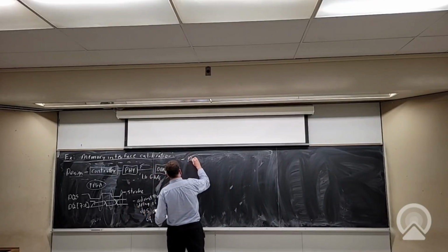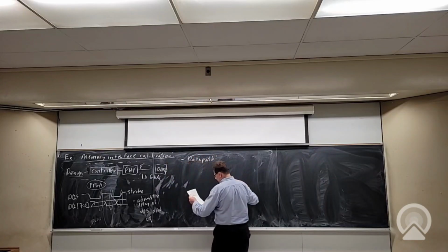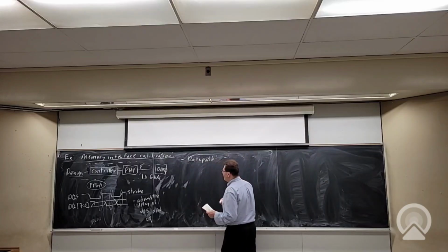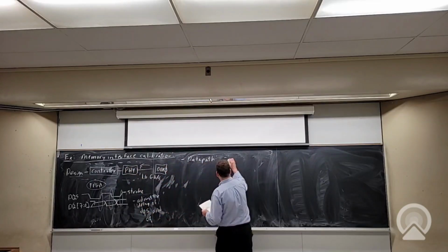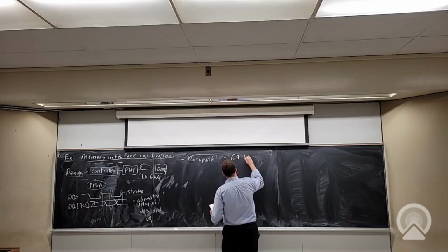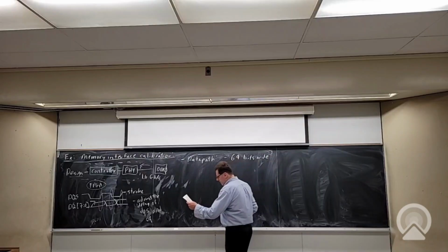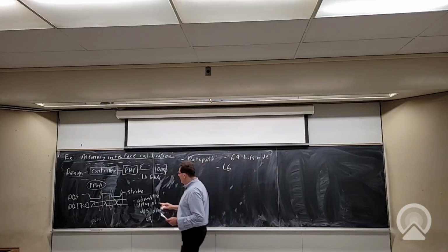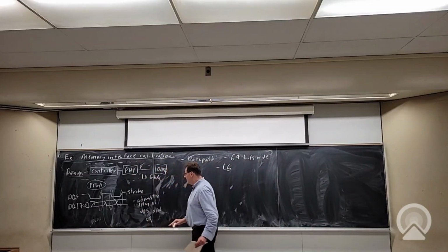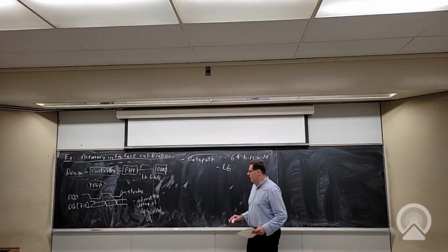So what does this look like? The data path is configurable. This is an FPGA, so you can ask for all sorts of things, but commonly it would be 64 bits wide. And the speed it's running at, at the I/O pins, basically these edges are running at 1.6 gigabits.